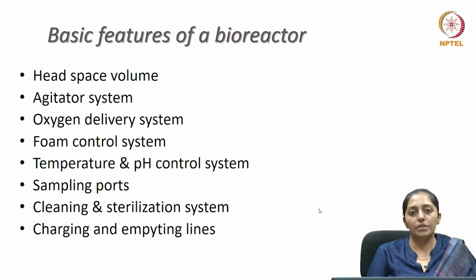Then sampling pods for sending the inoculum inside, which is the starter culture inside the liquid broth, and harvesting of the reactor through sample pods or intermittent sampling through sample pods. All this comes under sampling requirements. Cleaning and sterilization system, and then charging and emptying lines after harvest.